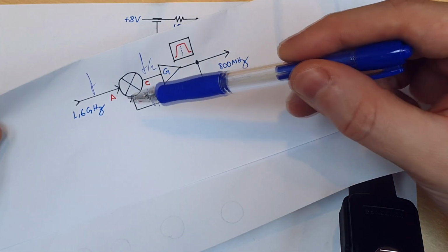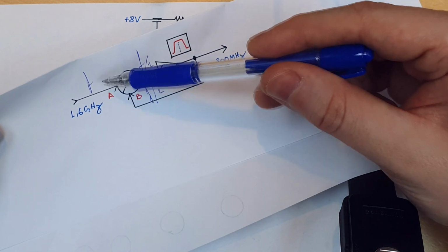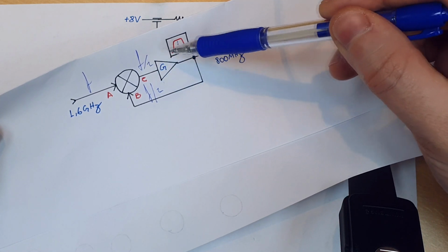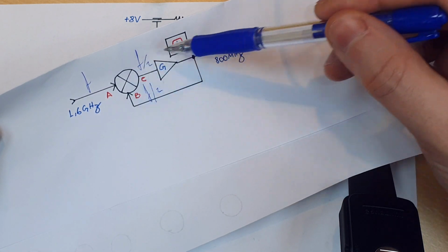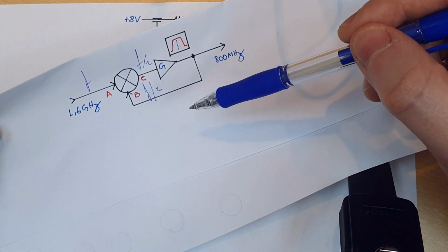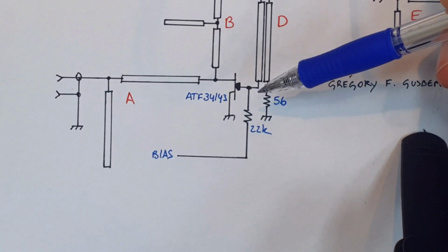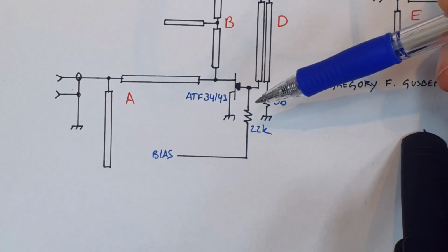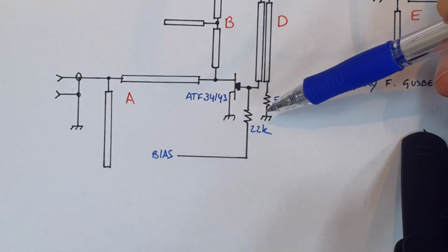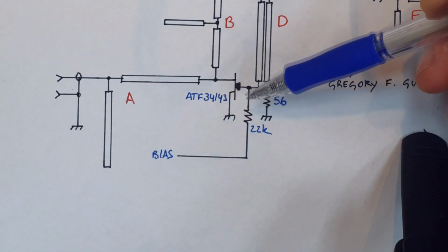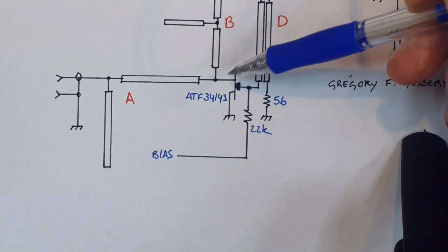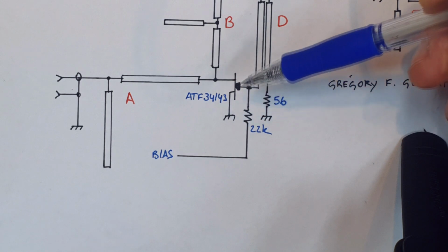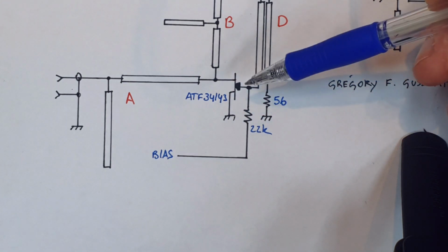It's very important to have a balanced mixer here, because if the high power of the input leaks to the output of the mixer, the amplifier will amplify the wrong frequency component and we will not have the frequency division we want. So the balance operation is done by this transistor acting as a passive mixer. This transistor is not acting in the active region. We have here only channel modulation. So we can see that we don't have bias on the drain of the transistor. So we don't have DC current going in the drain of the transistor. So we are not in the active region.